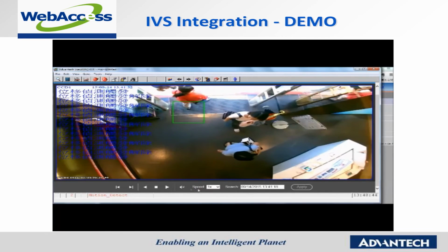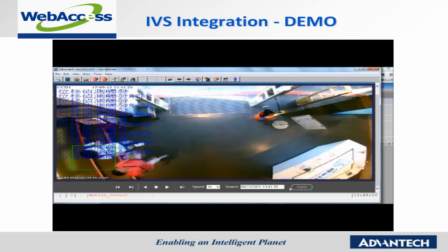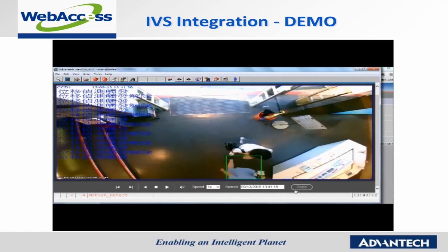Now the video images from IVS system have appeared in the window with indication of event trigger status. Now we can see that any moving object within the detection area is deemed as an independent event which can trigger an alarm in WebAccess. In this video, we can search and play back images of requested time. Have you seen the date on the upper left corner of the screen, which shows September 14, 2015? Now let's go to the time search bar to change the time to September 13, 2015. Enter, wait for data transmission, and see that the time shown on the upper left corner has been changed to September 13. Now you're watching video of September 13.